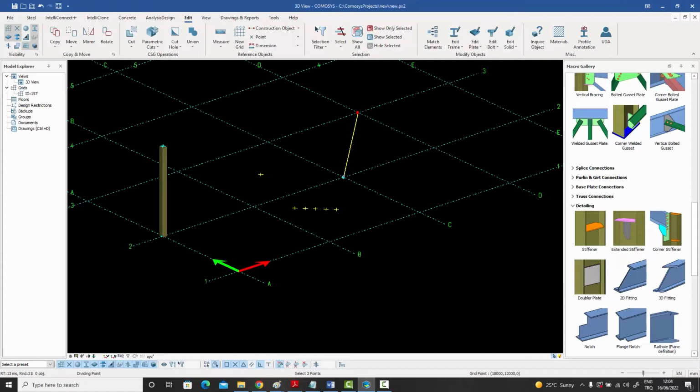Right now I'm going to press 5, and while keeping 5 pressed, I click on the other point. Although the setting inside is 1, it temporarily overrides that setting and divides the line into 5 points. If I wanted to divide it into 9 points, I would press 9 before clicking, keep it pressed, and click on the other point, and I get my 9 dividing points. This is pretty handy and very fast for creating new points.